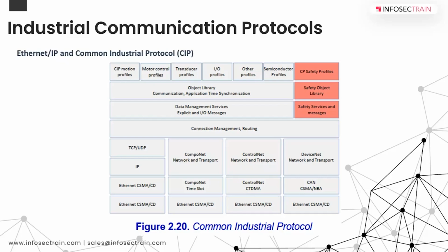And when we talk about explicit messages, they follow the client server or request response connection model. So what happens is the PLCs and HMIs, which you saw, exchange diagnostic messages and file transfers. The commonly used ports are a TCP port and a UDP port. The TCP port comes under the 44,000 something series, and the UDP port comes under the 22,000 something series. It is something I didn't recollect immediately.